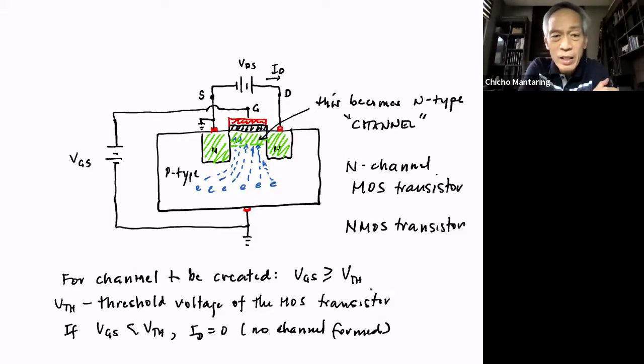Okay, and then Rick, what do you mean by Thevenin voltage? No. VTH is not Thevenin voltage. VTH is threshold voltage, not Thevenin voltage. Don't mistake this to be Thevenin voltage. It's a threshold voltage. It is a parameter of the transistor. So this is a transistor parameter.